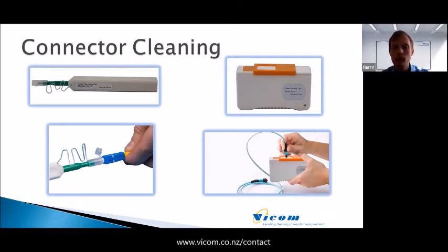so that every time you wipe the connector, it's essentially on a clean piece of fabric. Now, when you release the orange tab back to the left-hand side, when you then pull it again to the right, it exposes a new and clean piece of fabric. So every time you clean a new connector, you've got a clean piece of fabric for it.